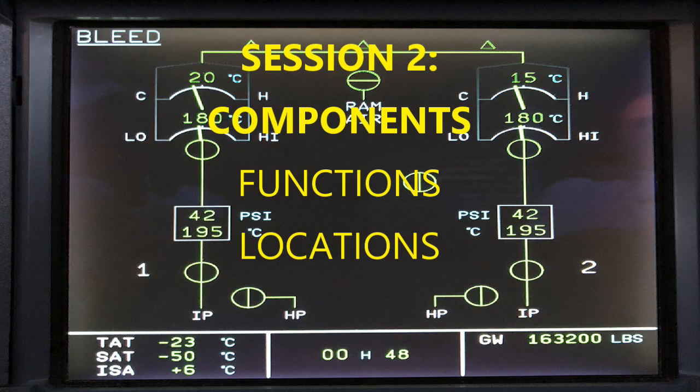That decreases the airflow, which reduces the pressure. Then 85 psig is another key number: at 85 psi upstream pressure, the OPV is going to fully close. Then it opens again when the upstream pressure decreases, to around 35. And of course, a lot of these valves have safety devices, so just be aware of that.